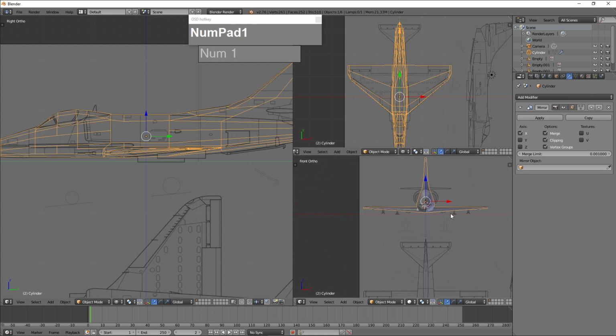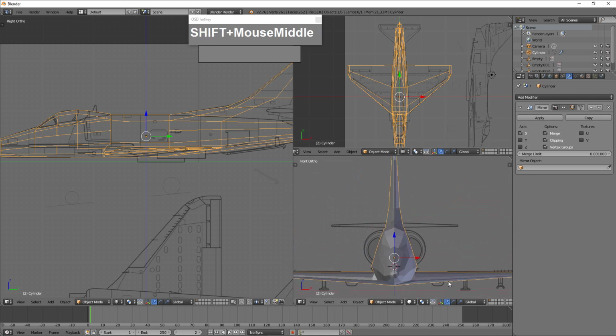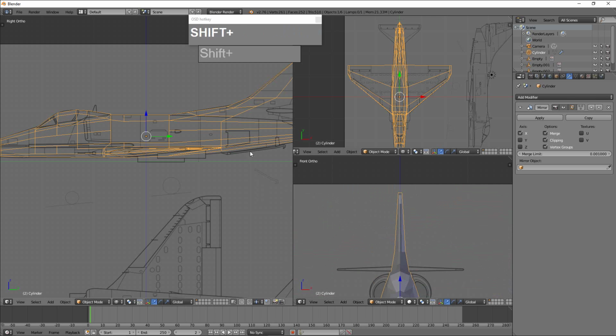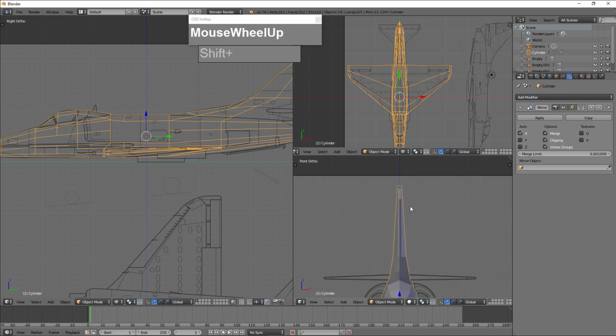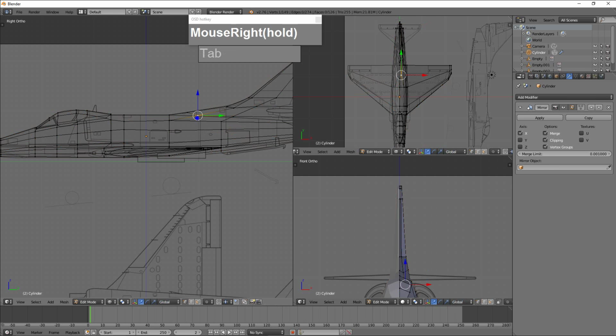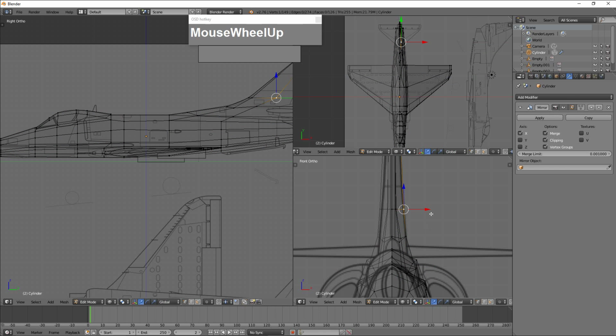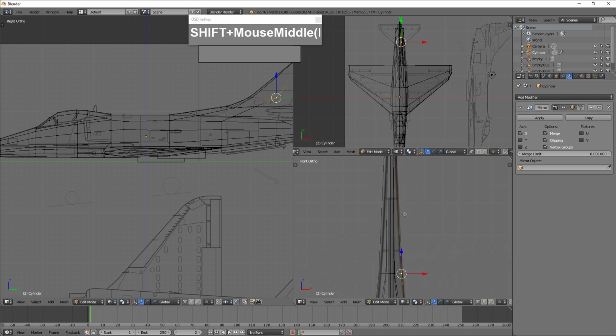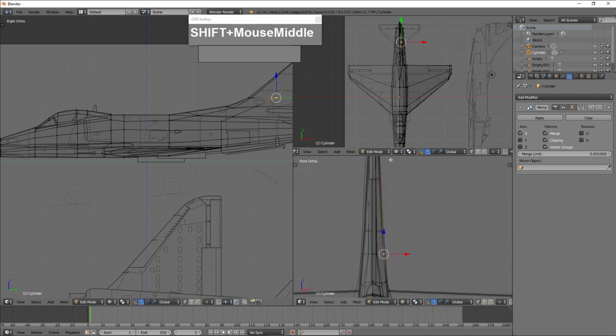Perhaps the dorsal fin might be a little bit too thick, so let's fix that by selecting the dorsal fin and making it slimmer. You can turn on wireframe mode and shift the vertices until it matches the thickness. Okay, so we got that done.